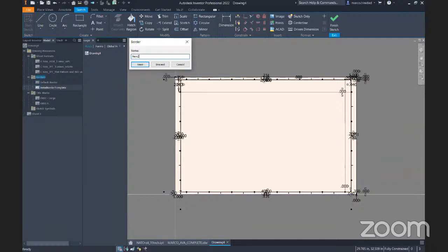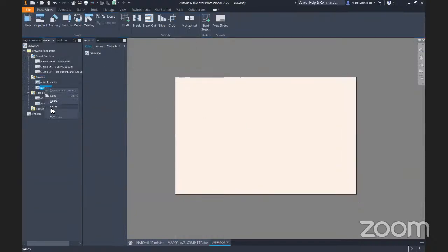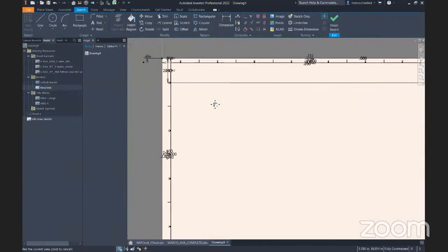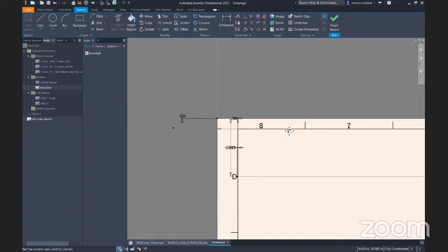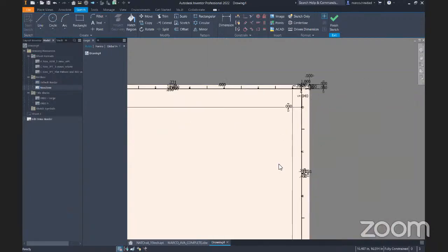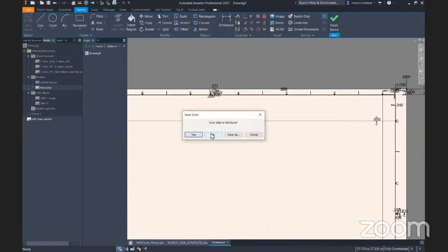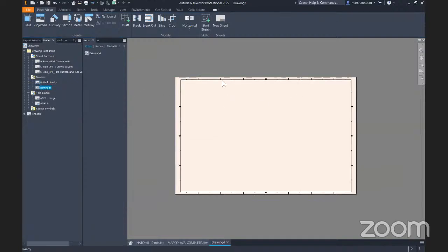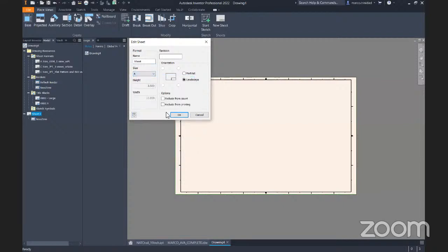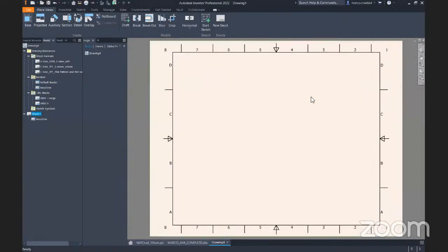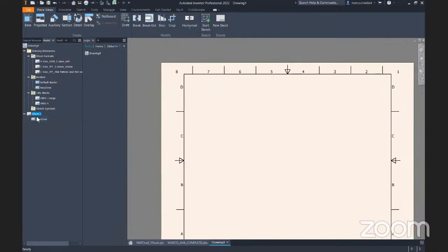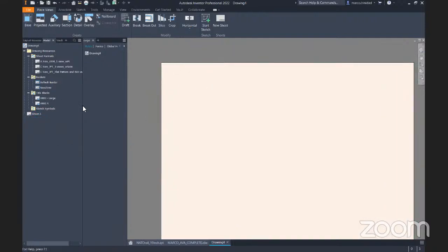A new zone to show you, and you can see it's parametric here. I'll go ahead and pull that up one more time under edit. It is parametric, so it is going to adjust if you change the sheet size. And that's one of the great things about doing parametric, is that even though I defined it using this specific sheet, if I were to go in here and change out the sheet size to maybe a smaller sheet, it'll go ahead and adjust the border to fit it. So I'll go ahead and delete this one for now.